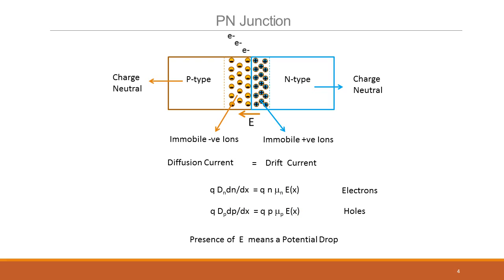Okay. Now you can see a field getting formed here. In the sand example, this was the frictional force. So not all electrons go from the N type to the P type. It goes till such a time that a sufficiently large electric field is formed, which opposes the motion of electrons. That's it. So it will find an equilibrium at this point.